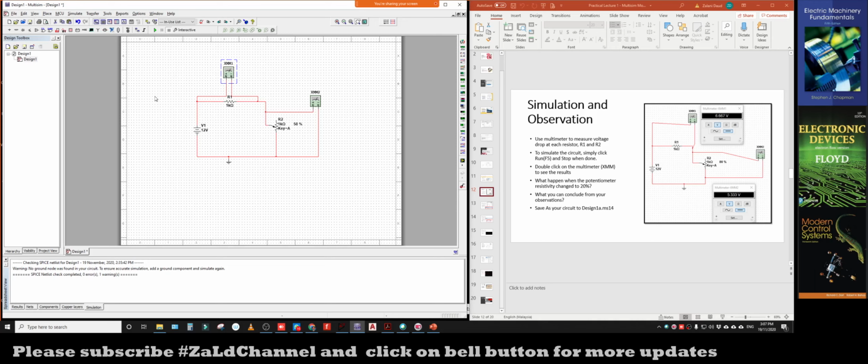All right. So once we finish this, of course, the next step is we would like to do the simulation. With the default setup, we supply 12 volt to a 1 kilo ohm resistor, and the other one is 50% of 1 kilo ohm, which is 500 ohms, or 0.5 kilo ohm. So this is half. This is 1 kilo. This is 500 ohm. So we want to measure voltage across this.